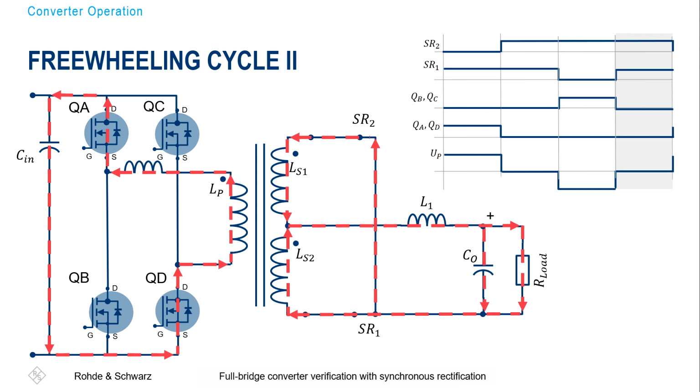Because what we will do later on, we will have to verify this switching pattern here, that this is correct. Because when you consider using a digital controller to operate all these switches, it is very important that because you are programming these switching states, they correlate to each other in a correct manner. And that is exactly what you have to verify later on.